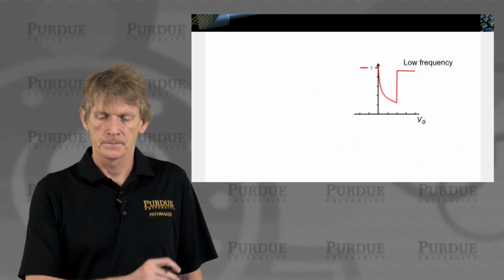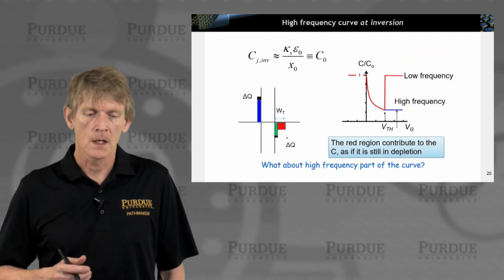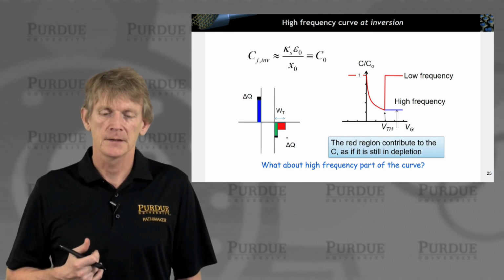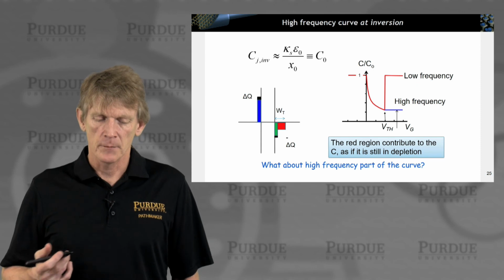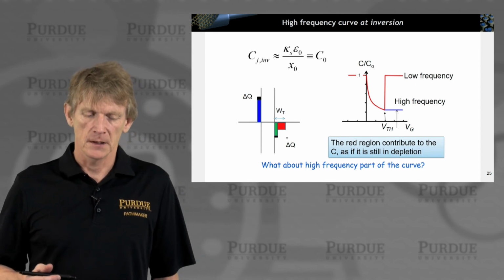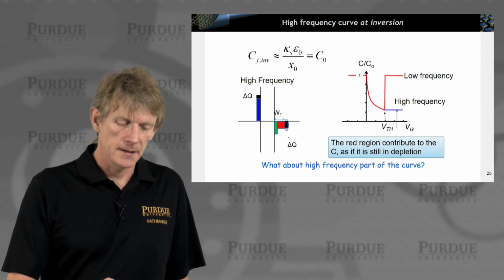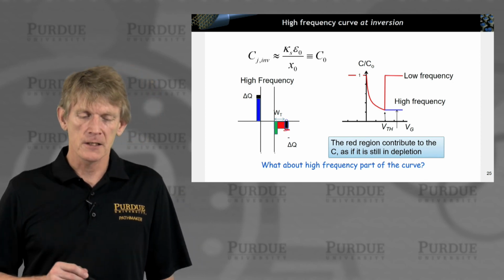Now, let's look at the high-frequency response at inversion. As I mentioned before, you really can only add and subtract charges at the tail end of the depletion region.